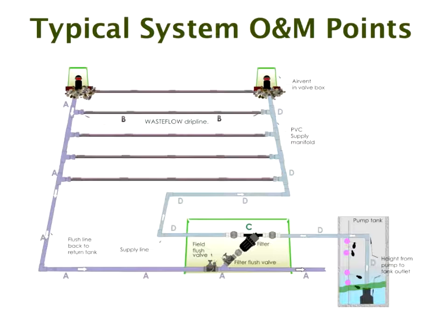One of the problems with floats is they're not 100% reliable, so they do get tangled up, and they're mechanical. So it's a good idea to pull the floats every 6 months and just check that everything's working correctly and put them back in again.